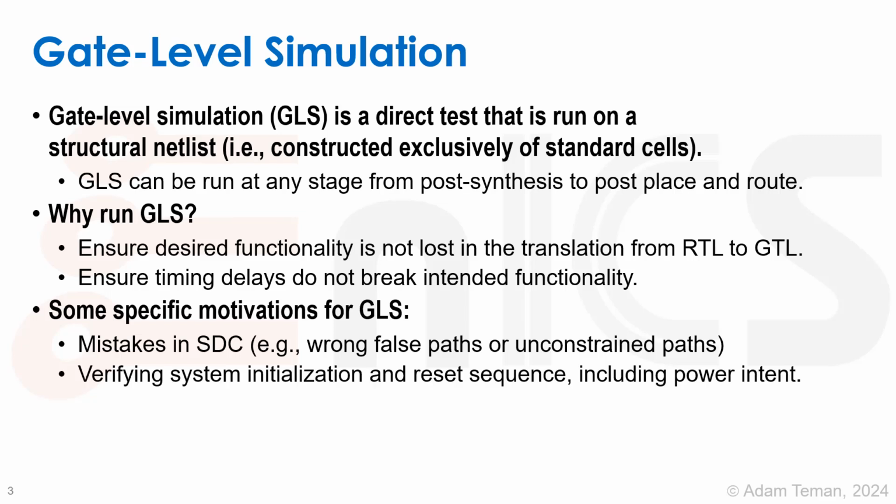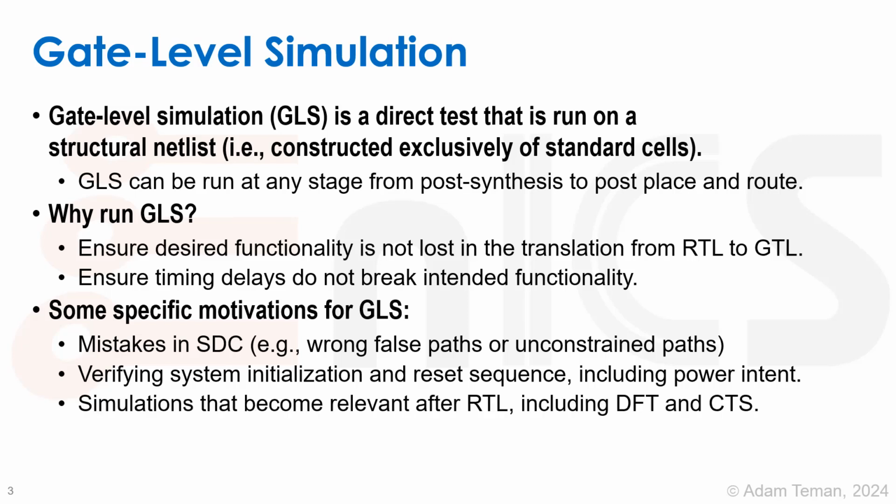Verifying system initialization and reset sequences, including power intent. This is an important thing because when we turn on our system, that's really a high point of failure. So at the very minimum, we want to check that we can boot up our system and take it out of reset at gate level. And this is also important because when we do low power things that I'm not going to really be discussing here, putting in all kinds of power gates and retention flops, we need to see that the power intent that we had when we were designing actually came out and is still functional correctly when we have our final design.